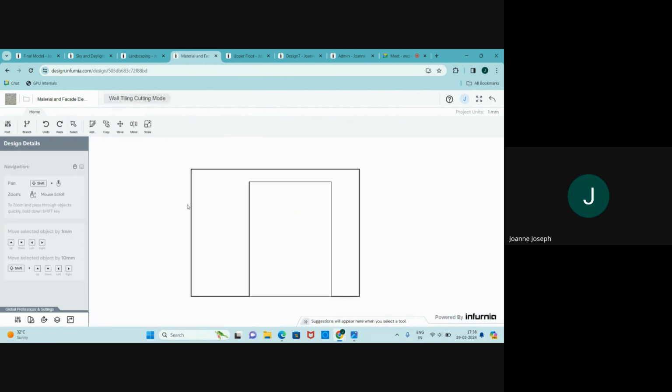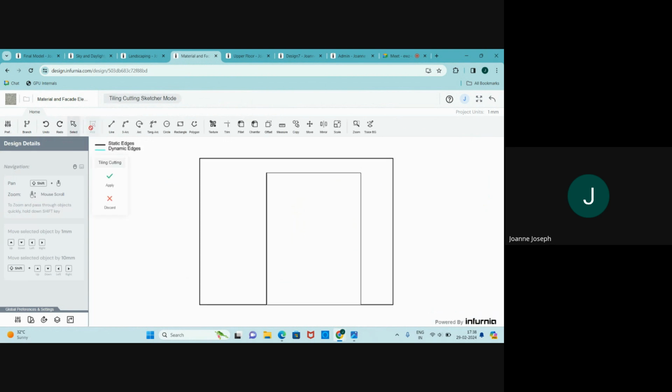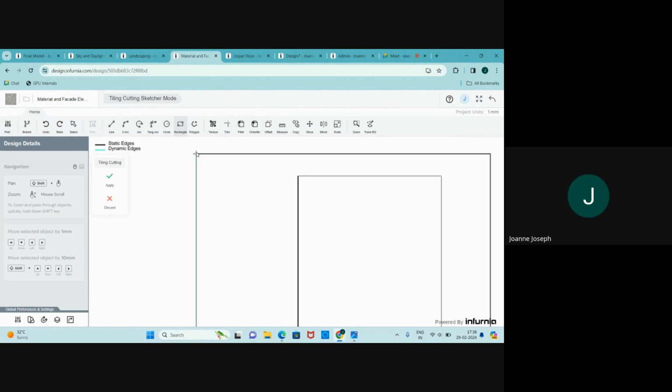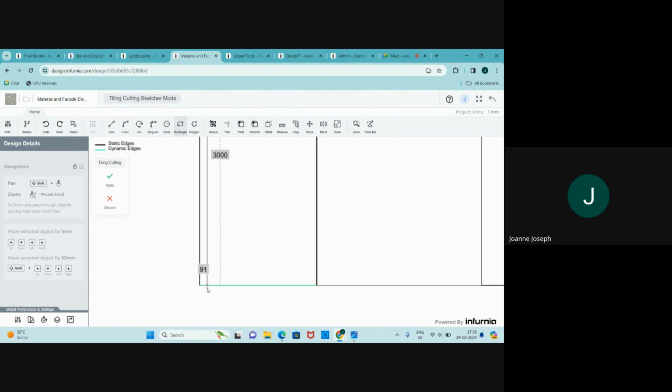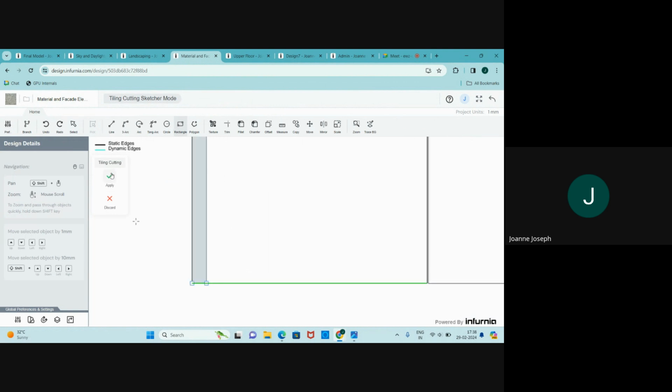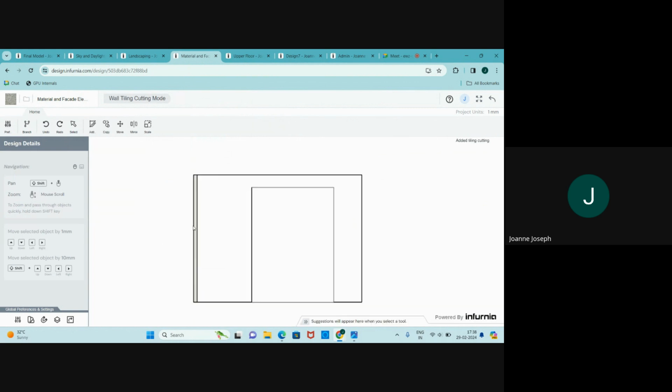So let's say I want to add just one louver. I select add. I create this rectangle here. I'll make a very thin one and then I will select apply. Now this is acting as one louver. I'll make it a depth of 20 and I will extrude it. I'll treat this as an extrusion. And the front shift, I will shift it a certain distance in front of the wall, let's say 1000.